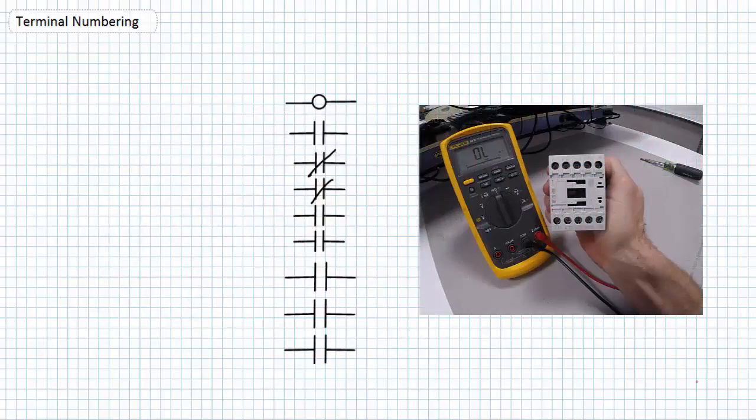Similarly, a contactor is characterized by a set of primary contacts that close when the magnetically linked coil is energized by pilot voltage. When the coil from terminal A1 to A2 is energized by pilot voltage, the primary L2T contacts would close. The L2T primary contacts are not included in the ladder logic diagram, but rather the primary schematic. Contactors sometimes feature an auxiliary pilot contact from terminals 1, 3 to 1, 4 that changes to its opposite state when the coil is energized.